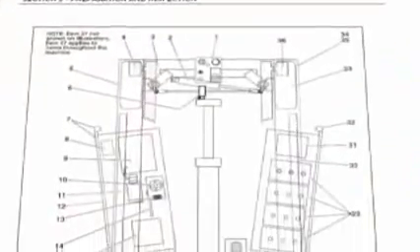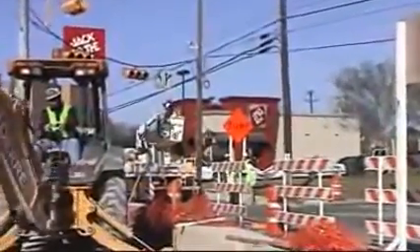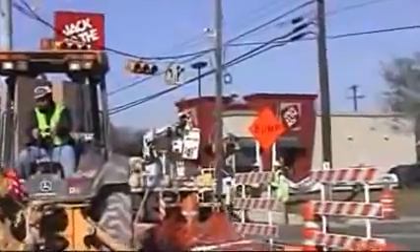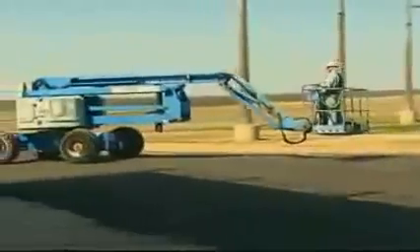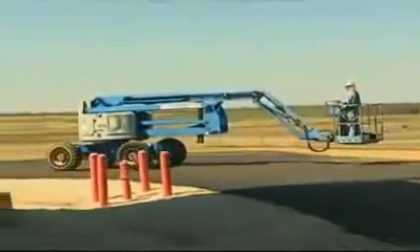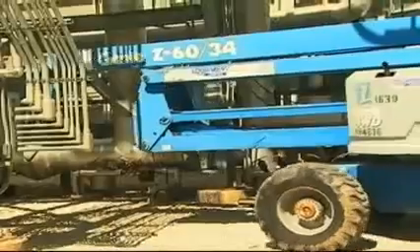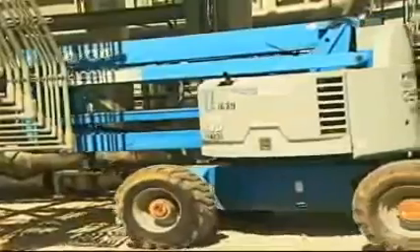Manufacturer's guidelines must always be followed. The first step is to ensure that the lift is lowered and safely resting on its support. If the lift is not on its supports, damage may occur to the lift as well as create a tipping risk while being transported. Always secure the lift to its supports while transporting it. This keeps the lift stable and minimizes the risk of unwanted movement.